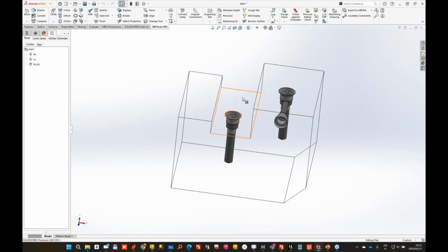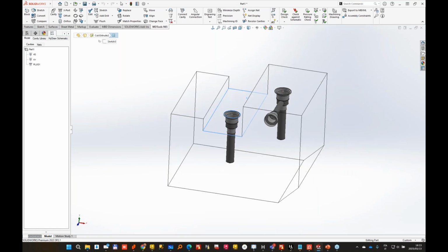So if you put the cavity on this face, then the depth in the drill chart or machining callout will be referenced to this face, not to the external of the manifold. And that's how MDTools is designed. So the geometry is defined from the face, and all the depths are referenced from the face where the cavity is lying.